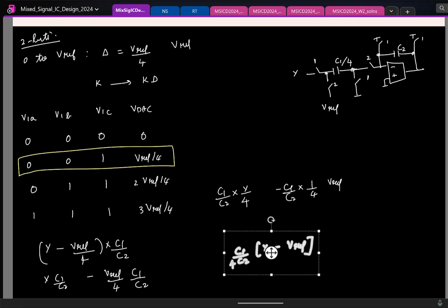If I have 4 parallel branches, each of them having a capacitance of C1 by 4, and if they also sample the input and transfer the charge, we are set. Which one? Oh, you use this way. The input is 4y. Yeah, but again, you can do this, but which means for this you need to have another amplifier. Right? In a simpler case is to do this.